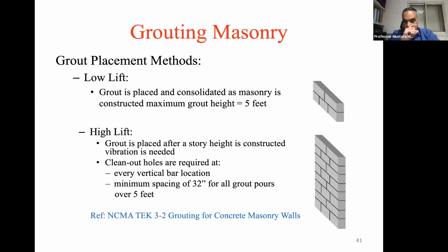So we have to make sure that that's done. And actually, many tests in the field, unfortunately, just use a hammer, looking at the grout in the cells where we have rebar, and we discover that the grout did not reach there. So that's an important thing that needs to be checked.